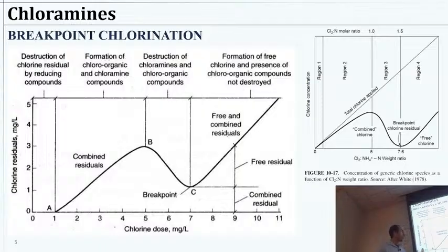So when we start adding chlorine, and we'll see at the very beginning if this is some typical water with some of these chlorine demanding agents, we will get no measured chlorine after adding maybe, let's say, 1 milligram per liter. So despite adding some, we measure 0. Okay, so that's going to satisfy, it's going to destroy or oxidize anything that's giving that instantaneous demand. After that, we have what we might call the combined residuals. So we are reacting with these ammonia compounds.